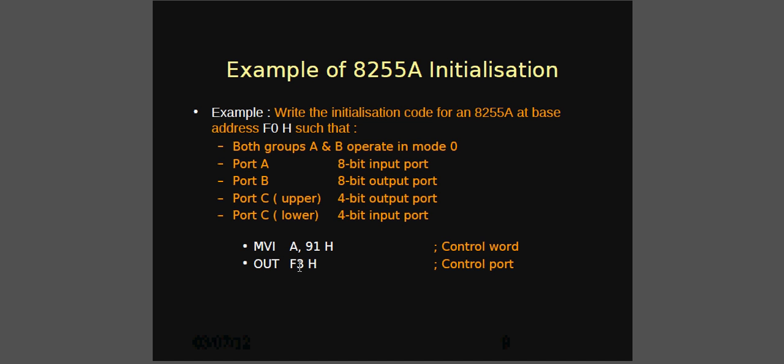F0 is the base address for this chip. So the F0H is the address that refers to this chip where we connect the input and output devices.